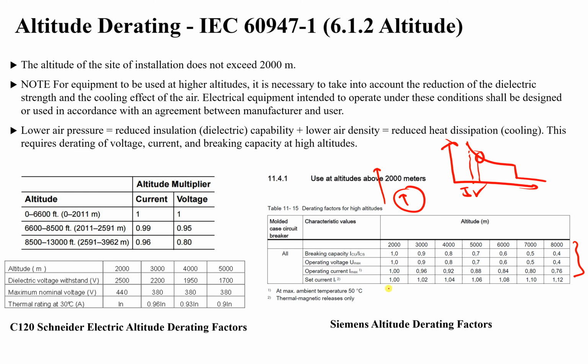So when we set our current at a higher value, we make it trip later, as if instead of having a 16 ampere breaker I obtained a 20 ampere breaker. This is exactly the same as derating or choosing higher breakers.